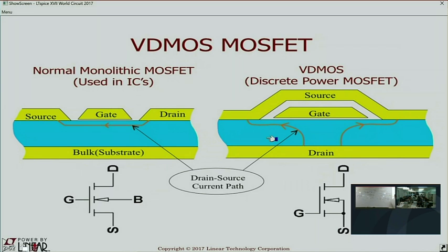At Analog Devices, we developed new device equations that encapsulate a new charge model for a vertical MOSFET. That's what's in LTSpice. If you want to use a simulator with a power MOSFET, just use the native circuit element. The third-party models cannot possibly switch correctly. The third-party MOSFET vendors, they have good intentions. They're doing the best they can. They're making models that will simulate in any SPICE program, but they aren't actually particularly useful. And actually, most of the MOSFET models in LTSpice are from the vendor. They send them to me.